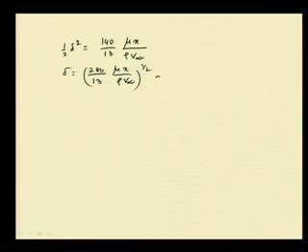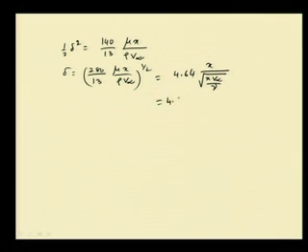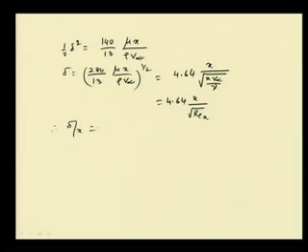Okay. And now, if we do this, we get 4.64 x, with a little bit of rearrangement, x V infinity by nu, and we know V infinity by nu is nothing but Reynolds x. So, we will write it as 4.64 into x by root over Rex, where Rex is the local Reynolds number. Therefore, we can write that the dimensionless boundary layer thickness delta by x is equal to 4.64 into Rex to the power minus half.